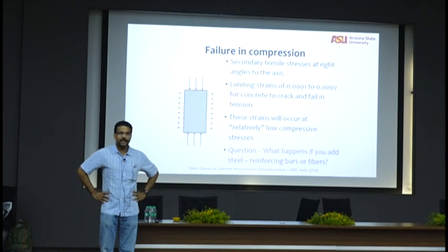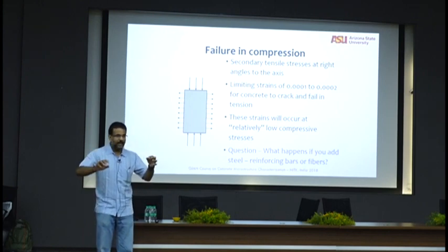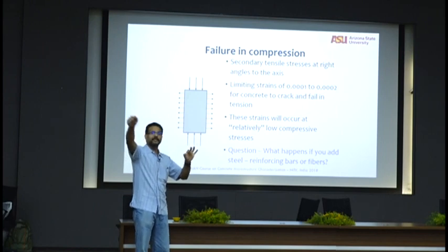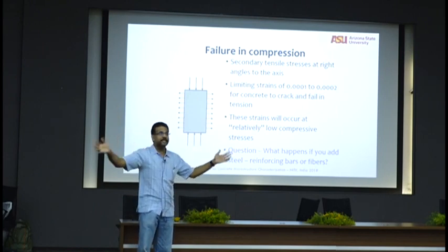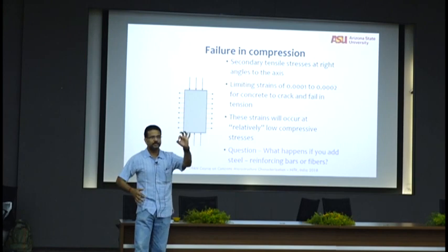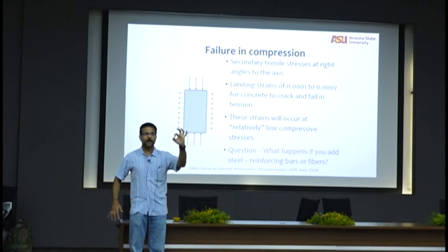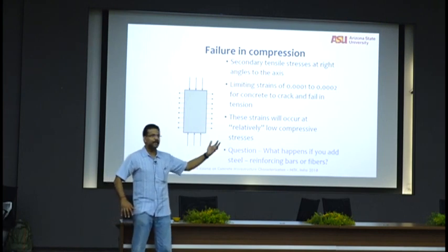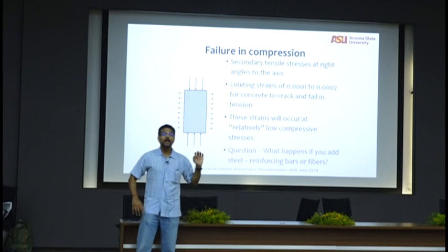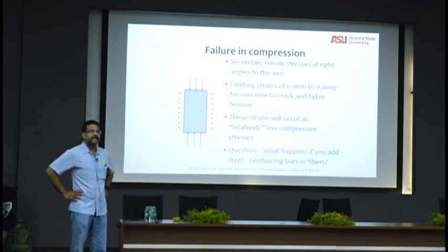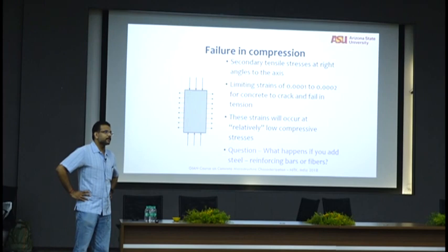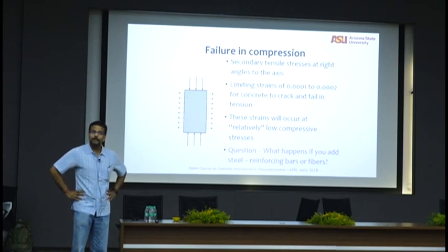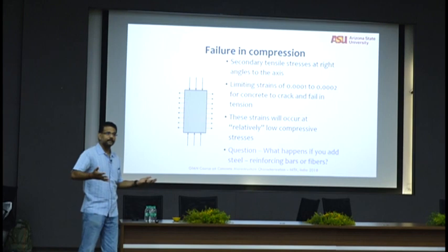Have you studied the idea of fracture at notches, right? If you have a notch and you apply a certain stress far away, the notch sees a much higher stress. If the notch is a pure sphere, it will see how many times more the stress? 3 times, right? So if you apply 30 megapascal, the notch will see a 90 megapascal stress. Now, if your concrete in that local area is seeing a 90 megapascal stress, for a concrete that you designed for 50 megapascal, what is it going to do? Locally, crack, right? You get the idea. All of you get the idea. It's going to crack locally.